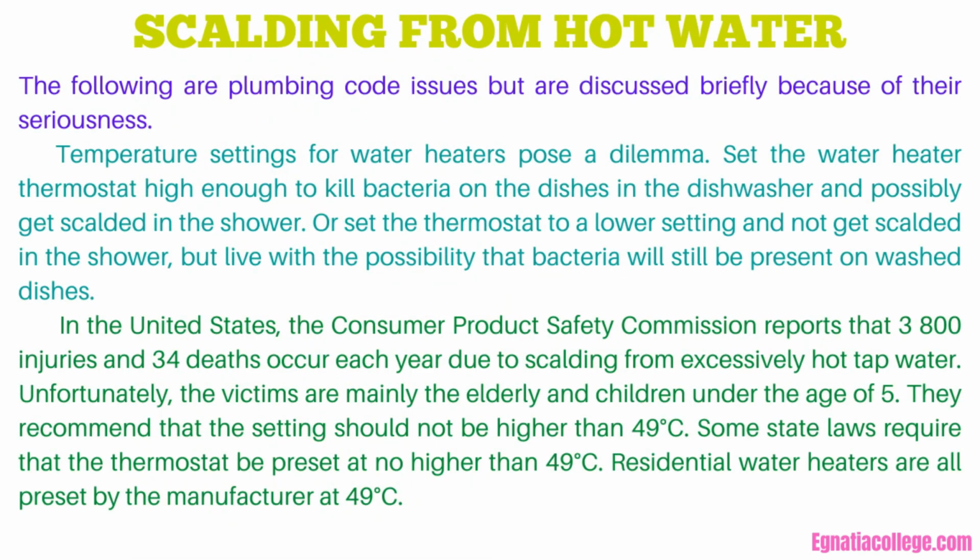Scalding from hot water. The following are plumbing code issues but are discussed briefly because of their seriousness. Temperature settings for water heaters pose a dilemma. Set the water heater thermostat high enough to kill bacteria on the dishes in the dishwasher and possibly get scalded in the shower.